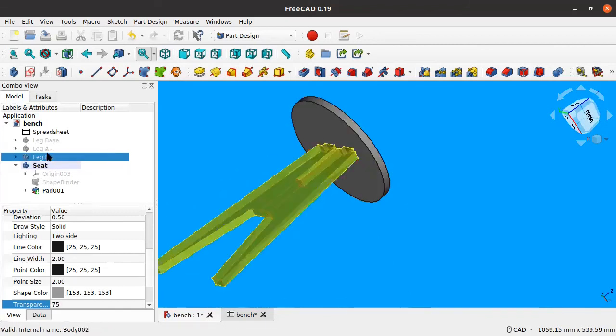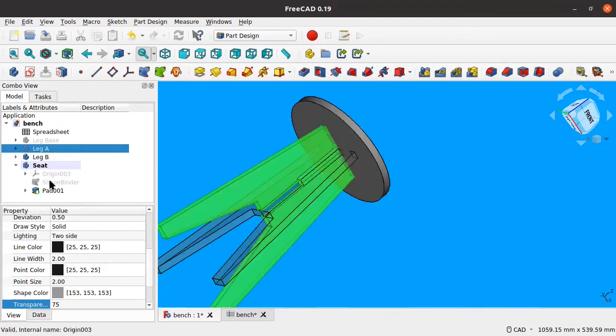So how do we do that? FreeCAD has this Boolean tool, which can do operations between 2 or more bodies in some cases. So basically you can select the base body and then subtract or add.